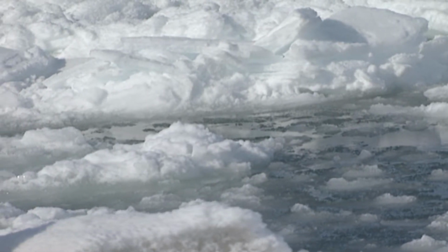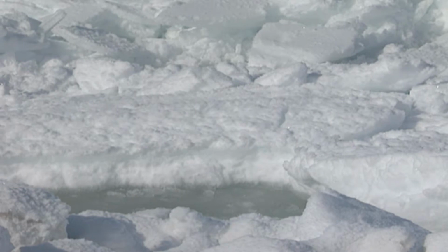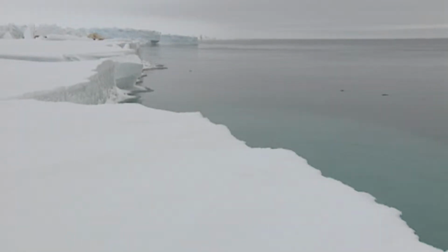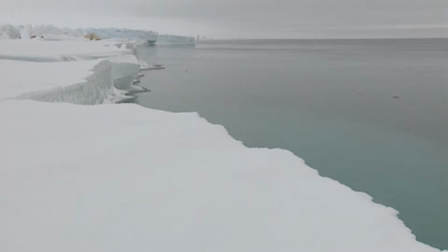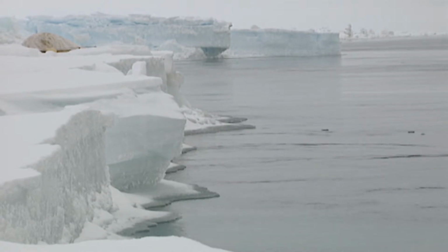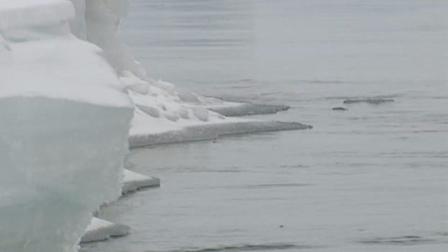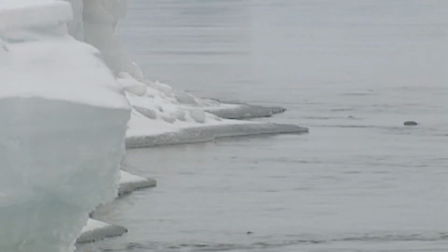What happens is she can get numerical instabilities occurring when portions of the model computations are not behaving well. For instance, if you make a water that's too shallow and your currents are going too fast because you've got strong tidal currents, then you can get a numerical instability and try to create predictions of velocities and sea surface height that are so unrealistic, the model dies because it can't handle it. It knows something is so completely out of whack.